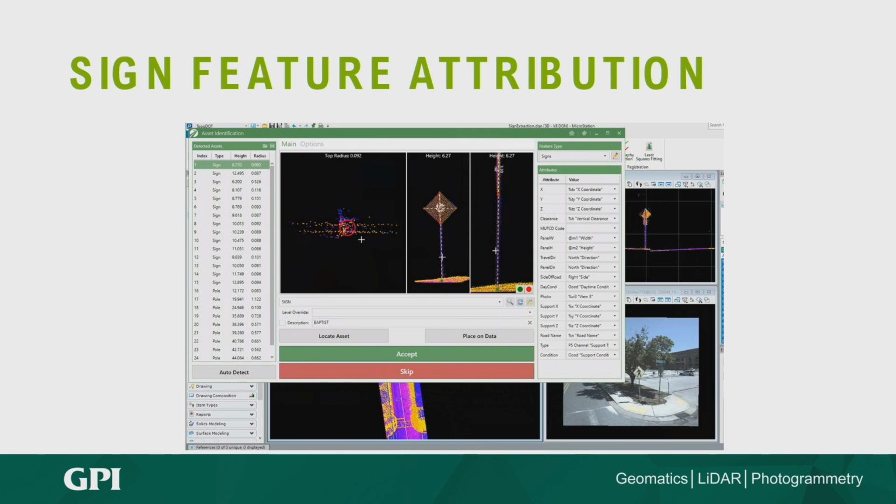For the actual attribution of features, so we've gone out, we've scanned everything. Now we need to locate features to build our database and attribute them. So this is an example of using the LiDAR data to attribute a sign feature. So you can see there's a whole list of attributes, including the coordinates, the clearance of the sign off the ground. We're looking at the imagery and determining the condition of it, good, fair, poor. The sign itself, the panel, and then the support. And then all of that can be used to update a database.